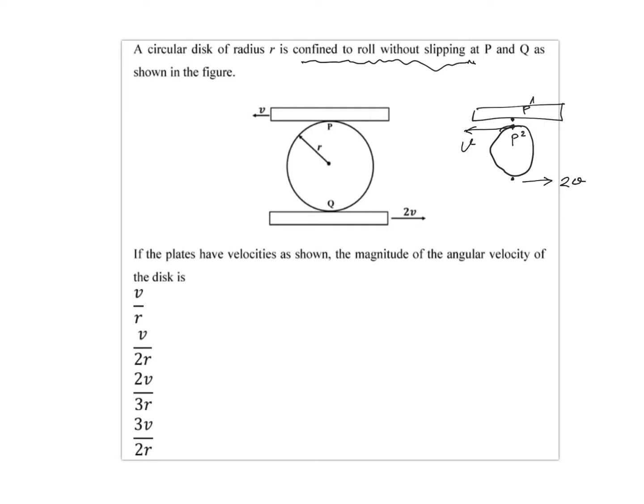This is slightly counterintuitive because you will be thinking, hey, I know pure rotation of a disk. Sorry for my poor sketch, but if I have a circular disk rotating in this direction with an angular velocity of omega, and the radius of the disk is little r, then we know this point will move towards the left with a velocity of r omega.